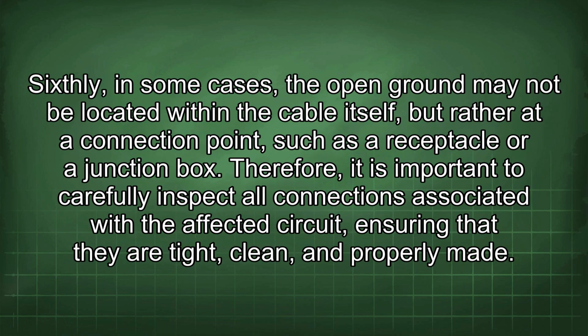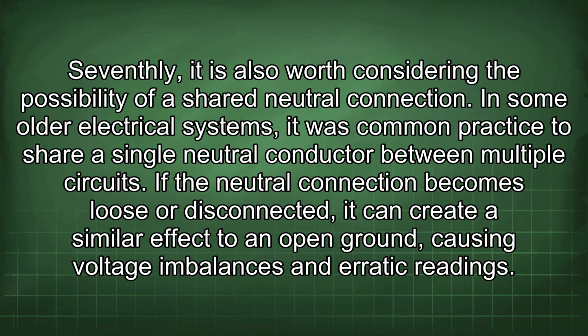Sixthly, in some cases, the open ground may not be located within the cable itself, but rather at a connection point, such as a receptacle or a junction box. Therefore, it is important to carefully inspect all connections associated with the affected circuit, ensuring that they are tight, clean, and properly made.